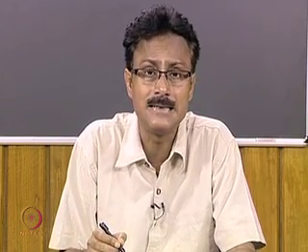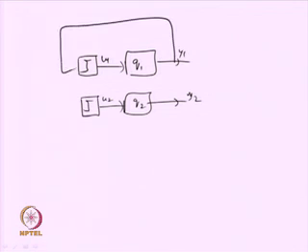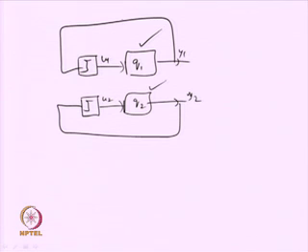Now, one can easily employ a relay here to identify the dynamics of the two subsystems. So, I can put one relay over here, I can put one relay over here, and then I can have the relay test, and consequently the parameters of Q1 and Q2 can easily be estimated. So, this is what we are going to do in this lecture.